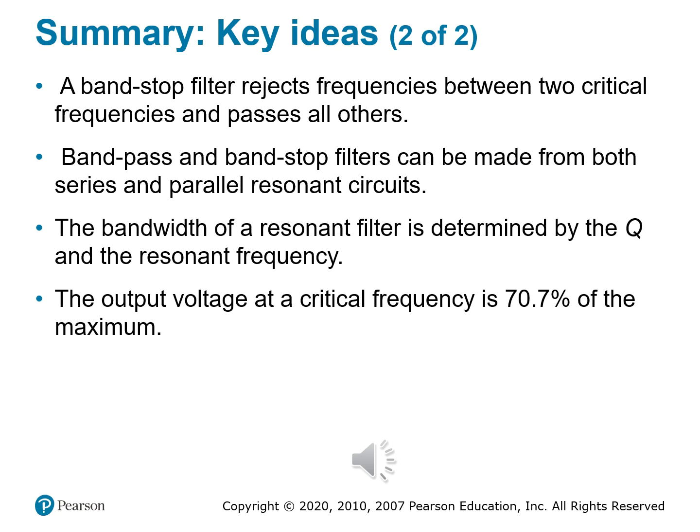If you have a very low Q, you're going to have broader brushstrokes on your canvas. Don't forget the 70.7%, that golden voltage rule. At a filter's critical frequency, the output voltage drops to 70.7% of its max. That's also noted as the -3 dB point, and it's your target when you're setting those cutoffs.